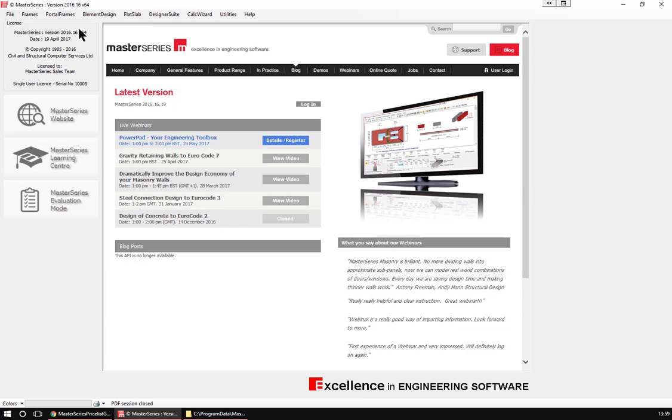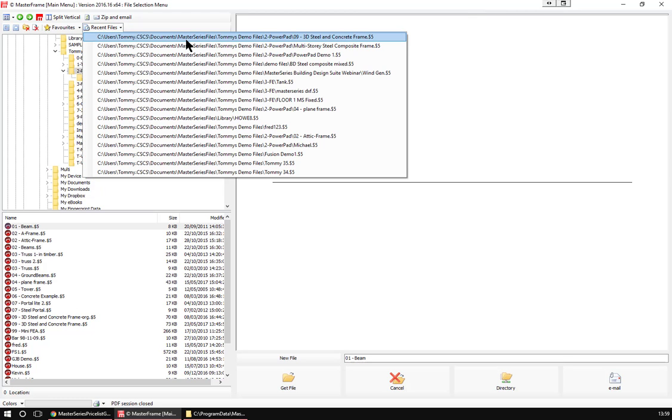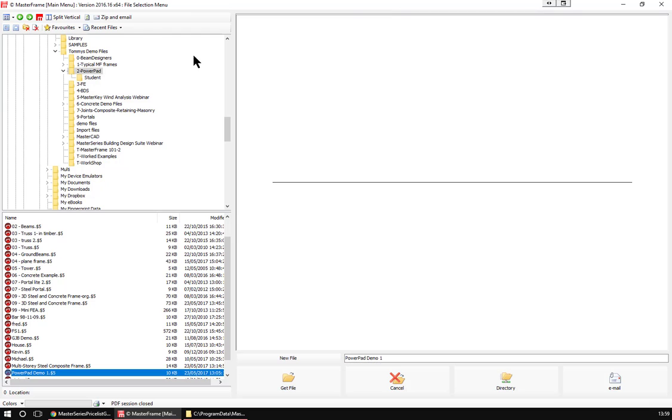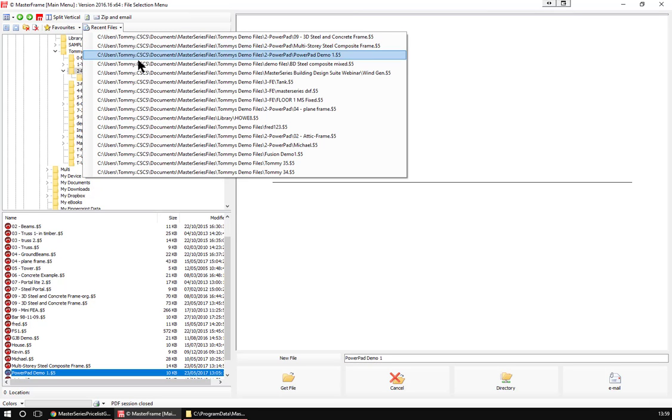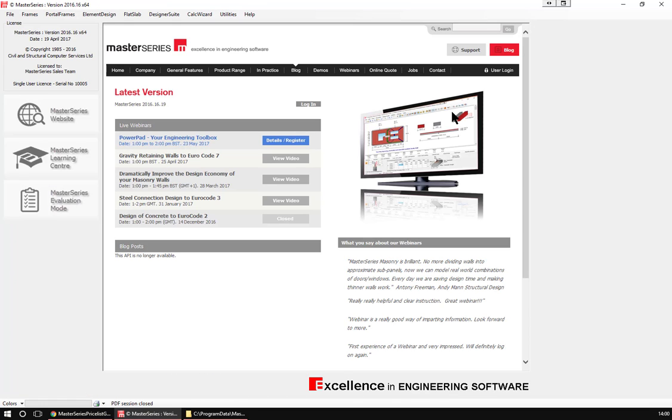So if I go to my little frame that I was playing with, I don't know if I actually saved it. I didn't actually save it. But basically, it was sitting with 2 nodes: the node that came with the frame and the node that came with the truss at the same location. Absolutely, and John's recognized that. But when I went to analyze the frame, it would have pulled those 2 nodes together and made them into one, and it would have automatically merged it.